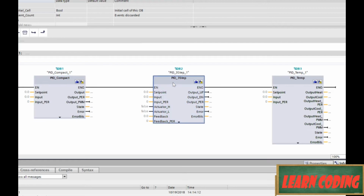Here you've got this 3-step, okay? And it says this is integrated for tuning valves. So if you're doing like a fluid process, chemical, water, something like that, and you've got proportional control valves that are being used to set a particular flow or volume in gallons or liters per minute, then this PID is optimized for that type of application.